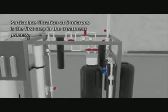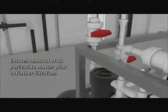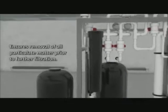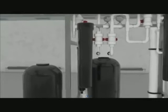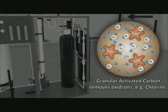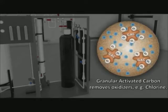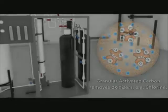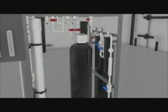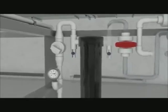Particulate filtration at 5 microns is the first step in the treatment process. This filter ensures that all particulate matter is removed prior to the next step of filtration, as well as less long-term maintenance of the RO membranes. Reverse osmosis is sensitive to oxidizers such as chlorine, typically found in all city water sources. Therefore, the process and water RO water system includes granular activated carbon, commonly called GAC. The GAC is an absorbent and will reduce the levels of chlorine being sent to the RO membranes. The effluent of the carbon column passes through a higher micron capture filter to capture any carbon fines that may have been released from the vessel.